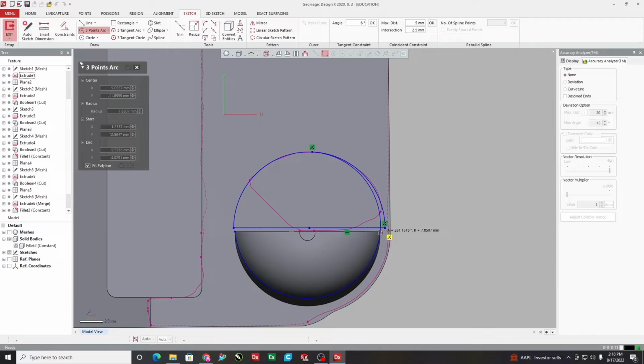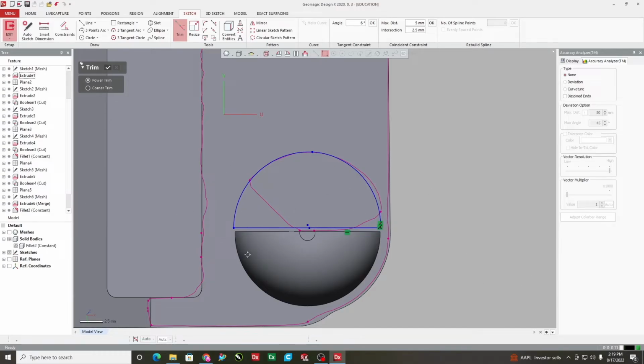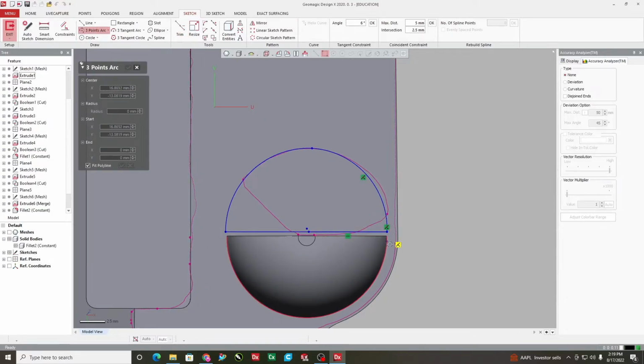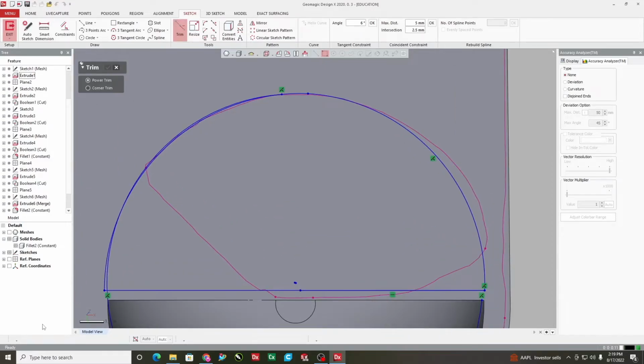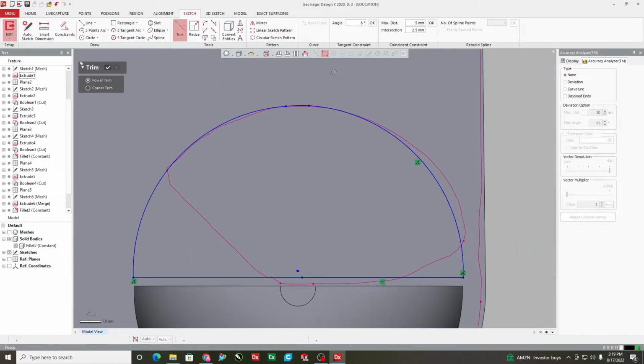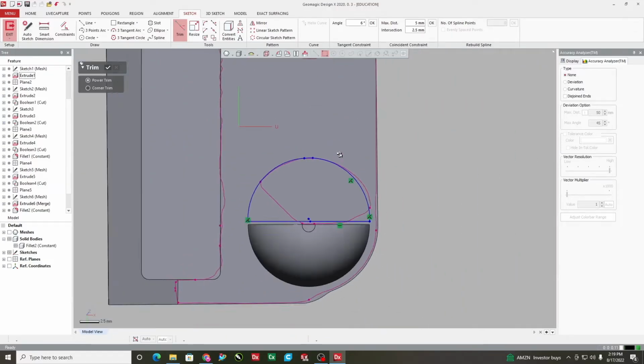So through this right edge of the upper dome also, I will try to see what is the issue. Sometimes when the edge is selected, that circular edge doesn't match perfectly with the virtual plane because the edge is distorted. So, because of the distorted circular edge, it is showing the larger circle. So, we need to now match it properly, and it was not the exact diameter.